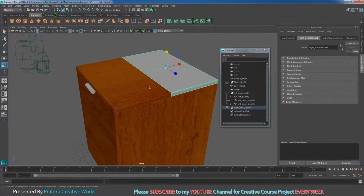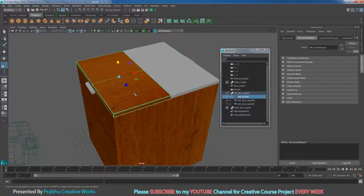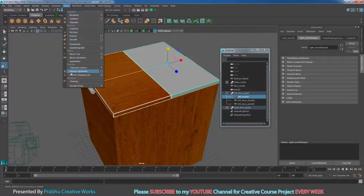We do not want to unwrap again and texture it in Photoshop. See here, this is the same object with the same faces, same edges and same vertices. That means you can transfer this texture to this mesh. So I will select this mesh, shift select this mesh, and go to Mesh and choose Transfer Attributes option box.